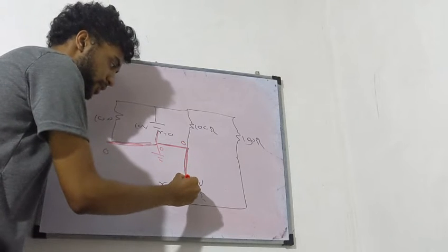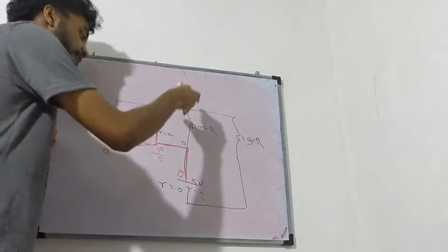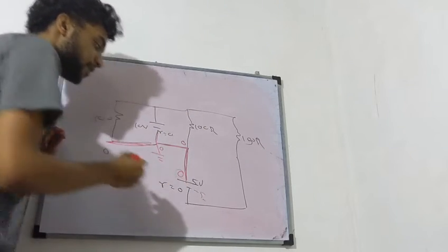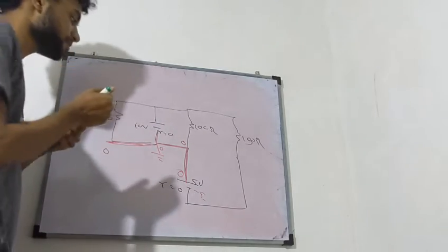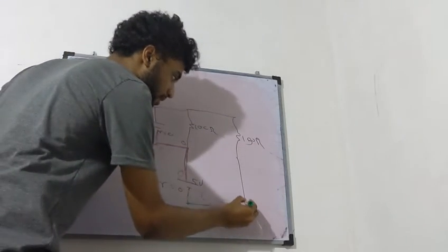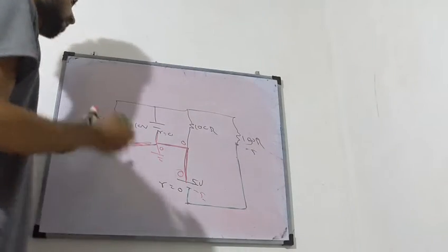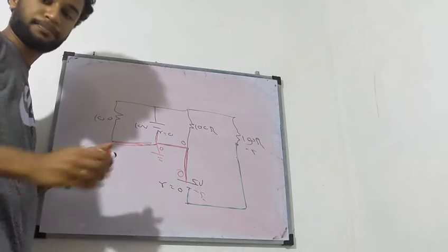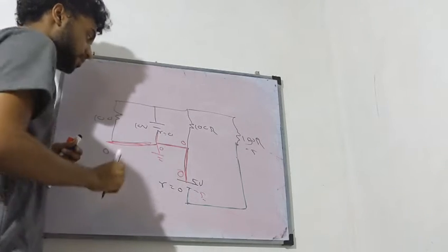Along this wire the same potential continues. If I make it 0 here, this has to be minus 5 because I would have the 5 volts potential difference. Then minus 5 continues along this line. Then I have minus 5 continuously. So here we go, minus 5. And now, as I've earthed this point, what can I say? I've earthed this point. What point? This point I've earthed.